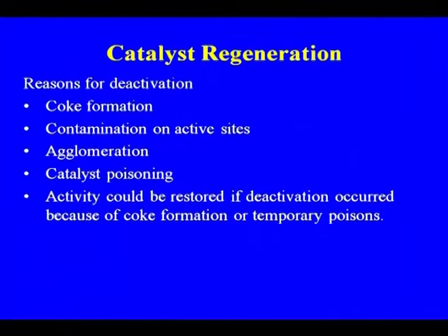Catalyst regeneration. Why do we need the catalyst regeneration? Because in all cases, whether catalytic cracking or catalytic reforming, the temperature is around 500 degrees and some coke formation is there; you can minimize it, but you cannot avoid it completely. The catalysts in all the cracking processes or the catalytic reforming which have been developed now have more resistance towards coke, so the coke formation can also be reduced.